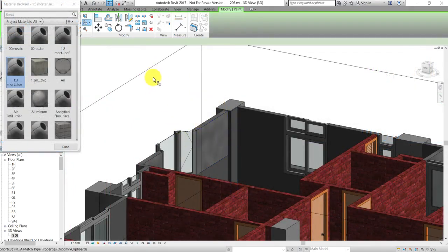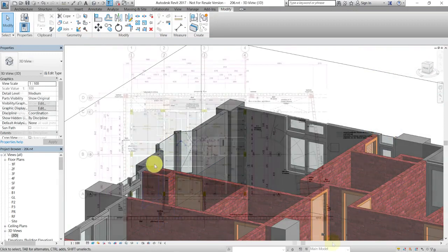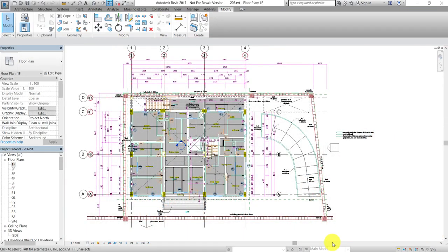Next, we move on to the walls in the entrance hall, the bathrooms, and the kitchens. The walls in these rooms are decorated with tiles and marble, and the thickness of tiles and marble will change the interior dimensions of the rooms. So we should use materials with thickness to model the tiles and marble. Let us use wall elements to implement the decorations.